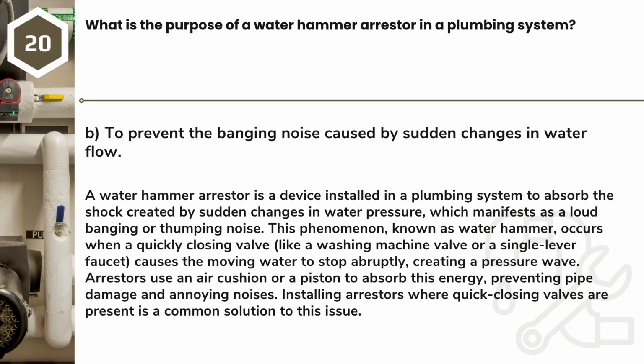Answer: B. To prevent the banging noise caused by sudden changes in water flow. A water hammer arrestor is a device installed in a plumbing system to absorb the shock created by sudden changes in water pressure, which manifests as a loud banging or thumping noise.